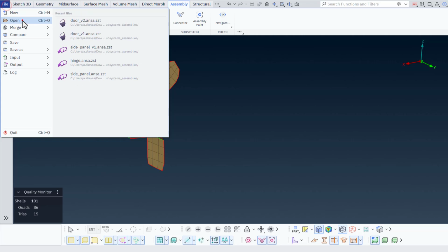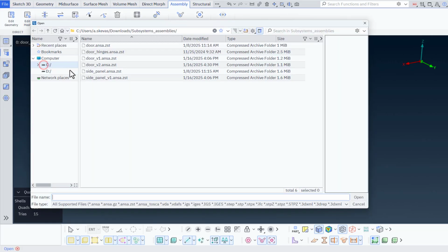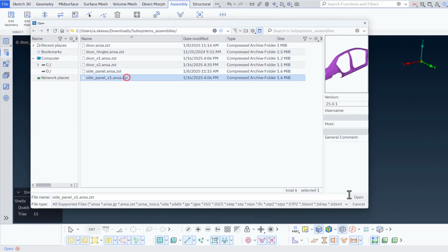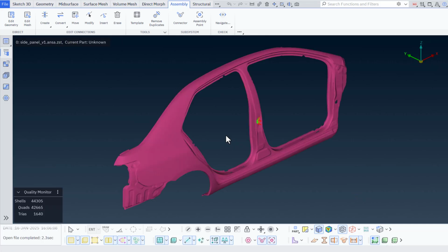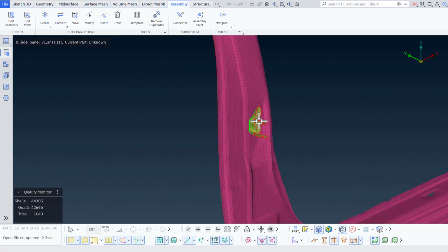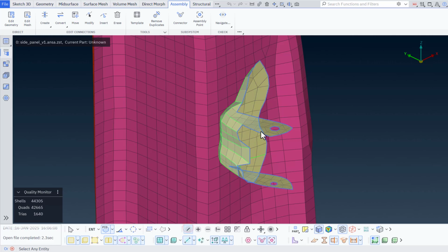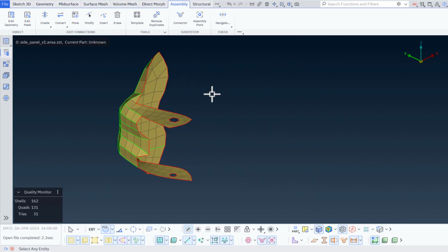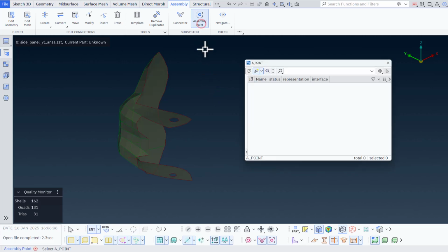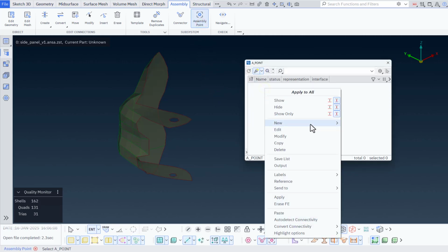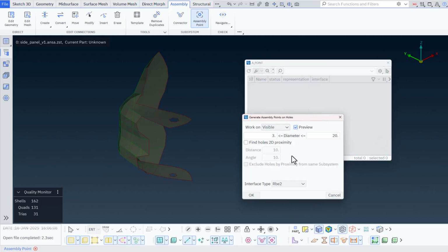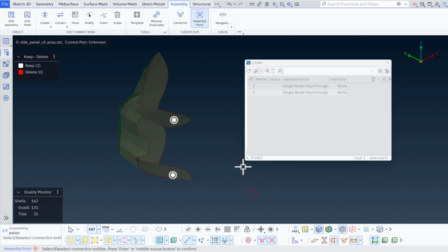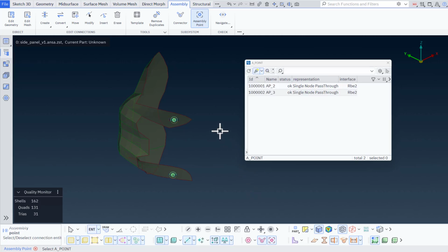Now that the assembly points of the first subsystem are created, the process is repeated accordingly on the second subsystem. That ensures that when the two subsystems are merged, the connectivity process is simplified. You can also import the subsystem, for example as an include, into the existing file. Again, using the On Holes Auto functionality, the assembly points are created. Save the updated file version.